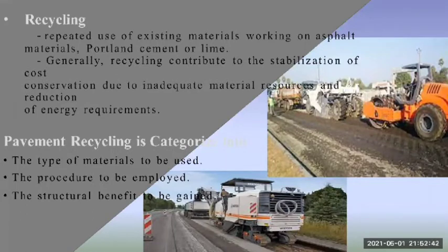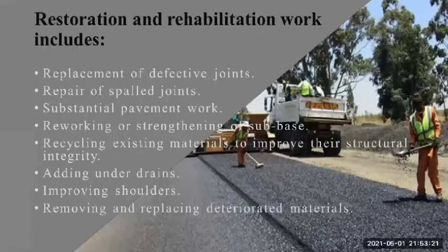Recycling is the repeated use of existing materials, working on asphalt materials, Portland cement, or lime. Generally, recycling contributes to the stabilization of cost, conservation due to inadequate materials and resources, and reduction of energy requirements. Pavement recycling is categorized into the type of materials to be used, the procedure to be employed, and the structural benefits to be gained.